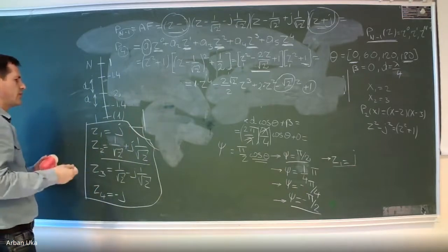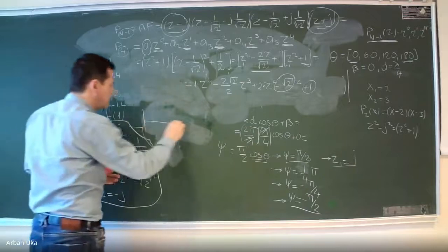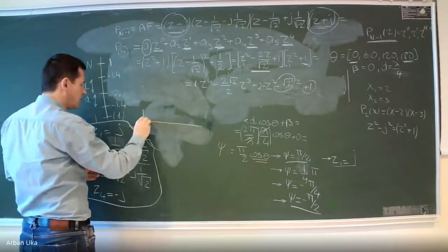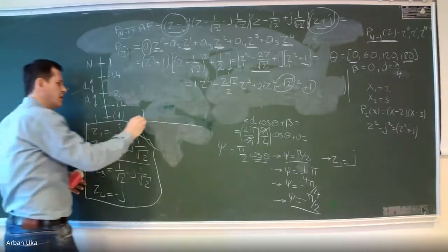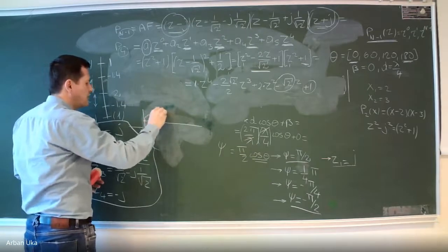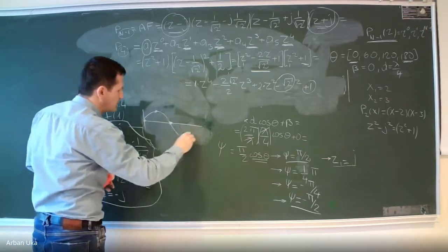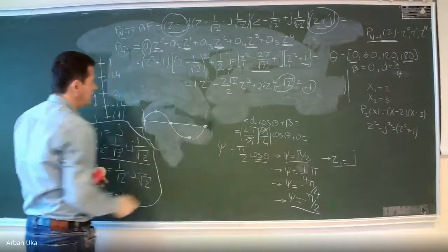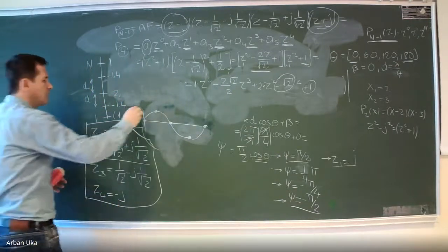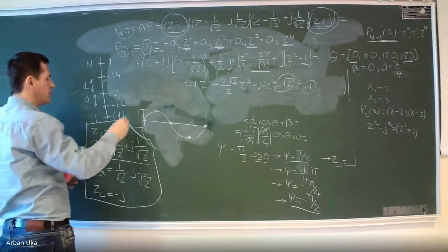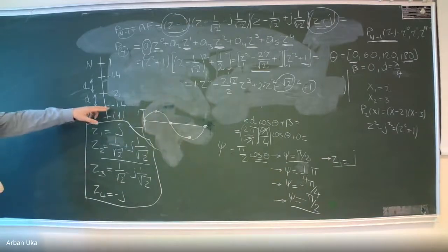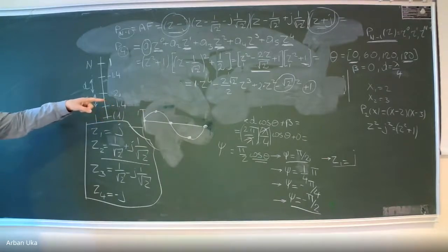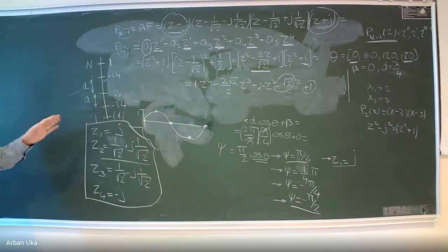The harmonic wave which will be fed into this antenna can look something like this. Amplitude is 1, and we can consider cosine or sine. Let's put a sine, it's not a problem. So we give a sine, after pi over 2 it will be maximum, then it's going to be 0 again here, and here. So this will be the initial excitation, with amplitude 1. The next component will be minus 1.4, but we can think of it as if the amplitude is 1.4 and the phase difference is 180 degrees. So it has a phase shift of 180.